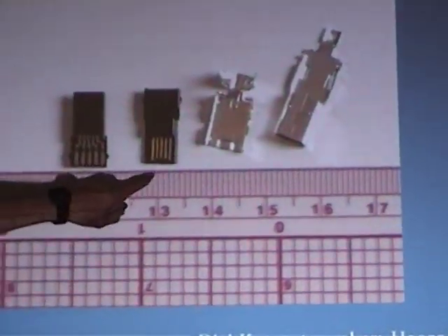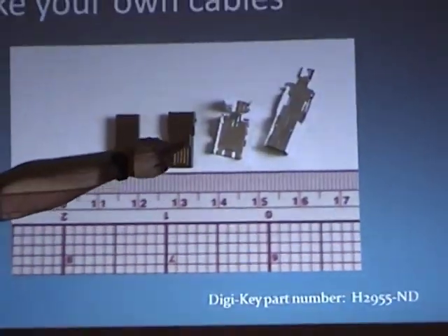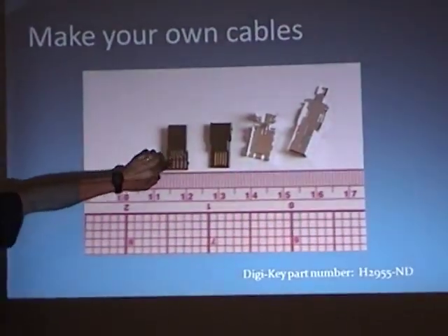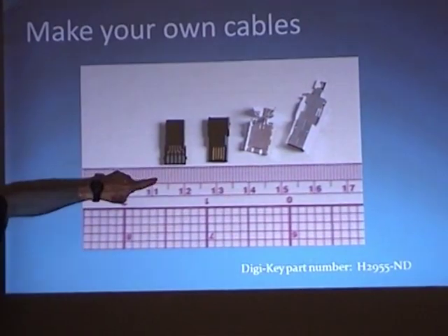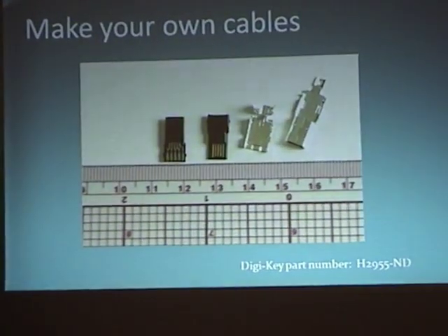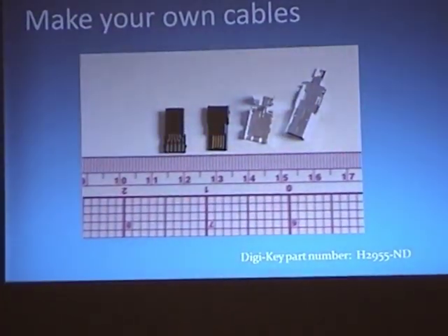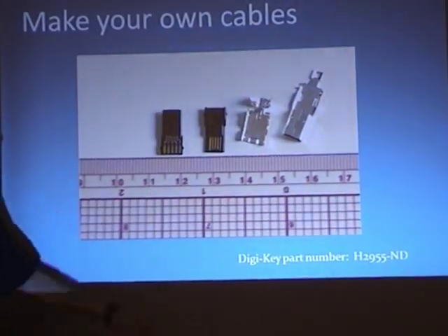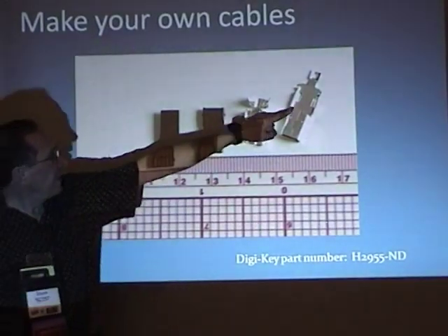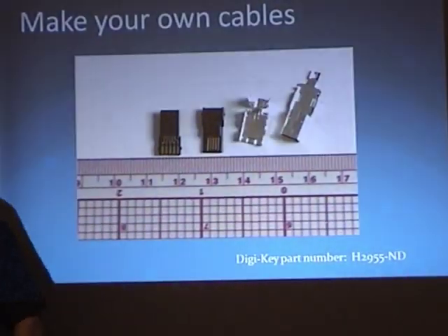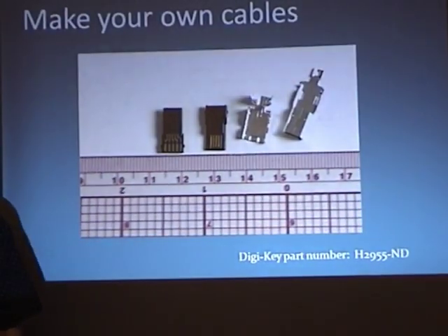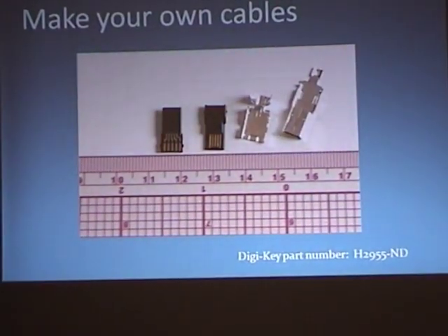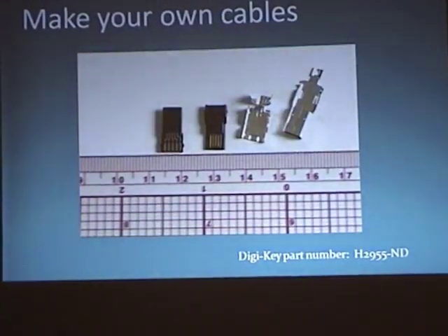And when you open it up, this is the end of the connector that goes into the camera. It's actually the backside of that you solder to. Now, notice again, these things are about 1 millimeter wide. If you've got a decent pair of magnifying glasses or decent vision, you can solder to this without too much trouble. You can also throw this part of the shell away, bend that part backwards, and this thing only extends out of a normal camera by a couple of millimeters. So you suddenly have really good, close connection without having to do a whole lot of fancy work.